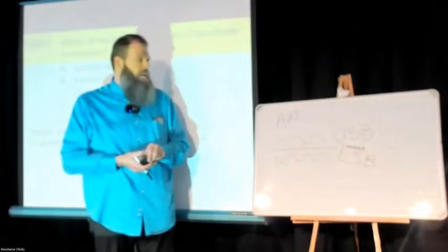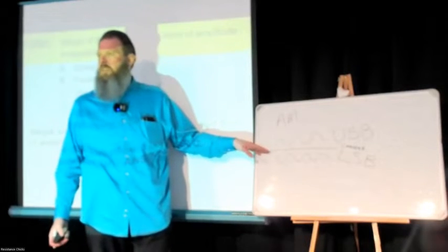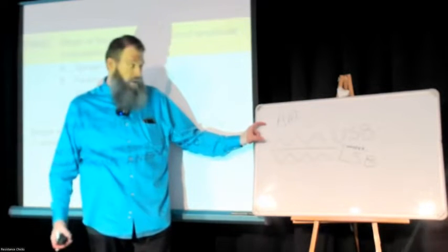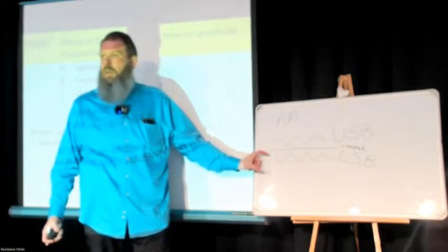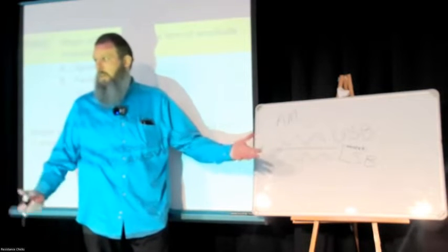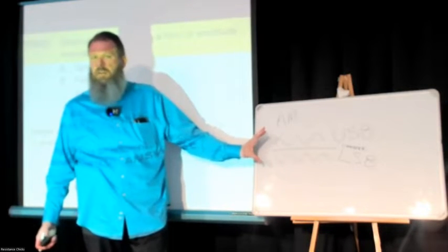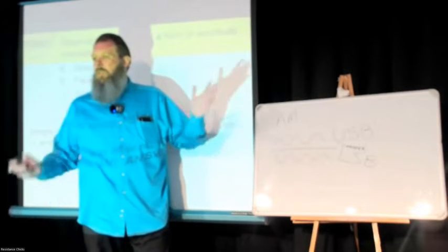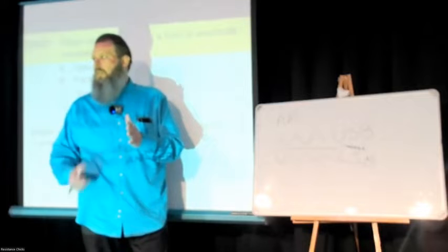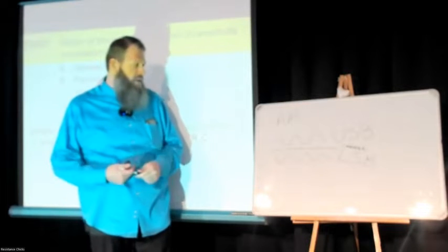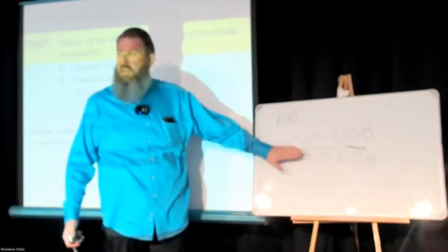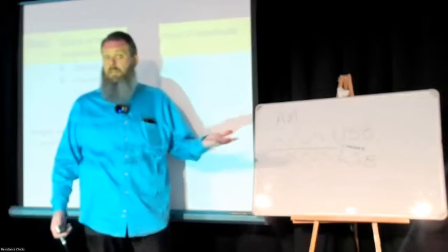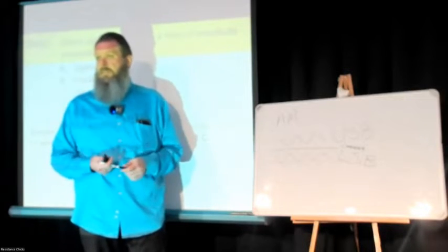You can understand that the carrier consumes some amount of space, the upper sideband consumes another amount of space, and the lower sideband consumes yet another amount of space. There are three components there. In order to reduce the amount of bandwidth so that you can go to single sideband, you simply eliminate the carrier and one of those sidebands, either the upper or the lower, and therefore it's single sideband.